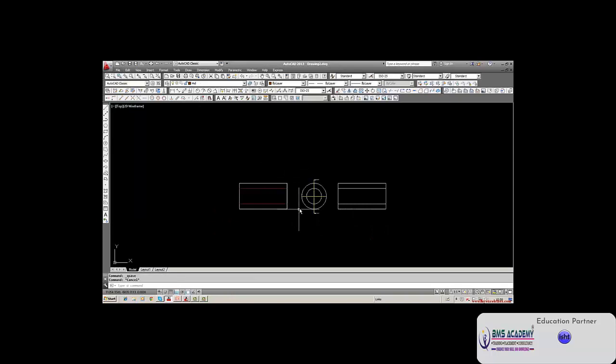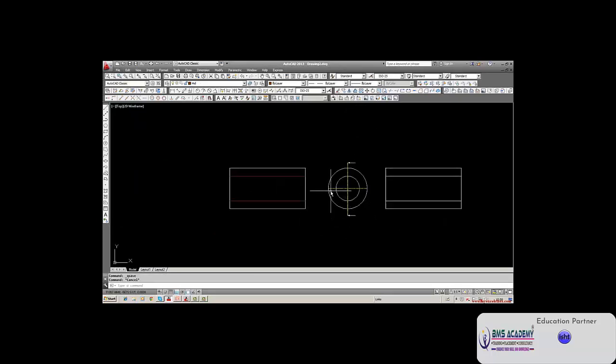So here in this drawing, section line and center line I maintain the same. When you take a section, this is what we can see. And normally in section, we use the crossed lines at the portion we have shown the section to indicate that it is the internal part of the material. So normally when you draw on a drawing board, you will draw lines very close to each other at 45 degree within this area and also within this area. Okay, so that also we can do in AutoCAD. I will tell you how we can do it.